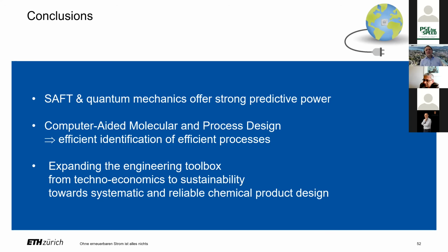No, yeah, thank you for the question. You're very right. In this application, I only showed steady state applications. But in principle, you can also design dynamic problems. This becomes numerically uglier because I have a mixed integer dynamic optimization problem. So we are fighting with this, but it can be done. We have been looking into the optimization of an organic Rankine cycle to put on a truck, where the exhaust gas is fluctuating in time. We can then take this into account in the design and also in the selection of the working fluid. So this is doable, but it's heavy.